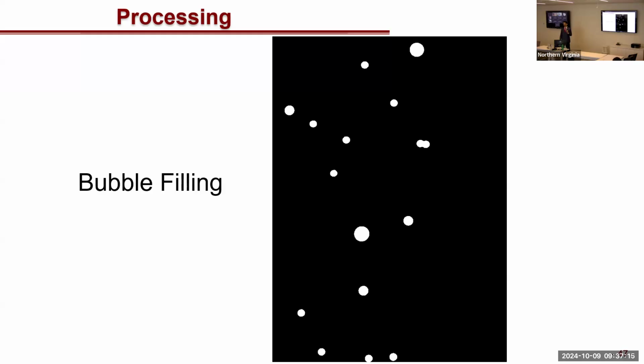As mentioned earlier, when the end condition of that flange is rough, there is a propagation of surface tension forces that allow an air pocket to form. If it's very rough, you can have a surface tension, so the bubbles kind of stick here, and so all that air injection rate is making a bigger and bigger bubble. It's not natural coalescence, where the bubbles come out and then they find each other, meet, and pop together. It's if many bubbles come together.